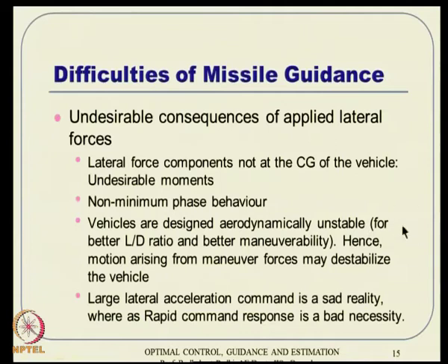They are not designed stable, by the way, they are designed unstable to have a better L/D ratio, lift over drag ratio, and better maneuverability also, because lift will be high and all that. Hence, the motion arising from the maneuver forces may destabilize the vehicle also. That means, if you do not do a very careful exercise, the vehicle is inherently unstable. So, if you excite it a little more, it will go to rotational instability very quickly. Okay.